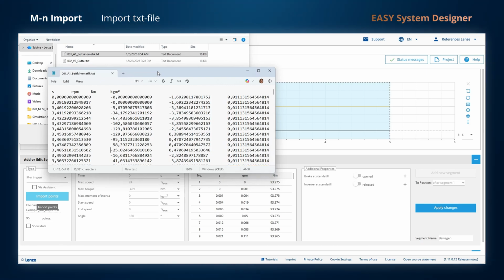The import must contain the signal curves for speed and torque. Optionally, information on load inertia, inverter lock, and brake may also be included. The load inertia is used in the drive sizing to determine the load matching factor. The file must be in TXT format, and it is recommended that you map a load side motion cycle of the machine, including downtimes, to describe your application.